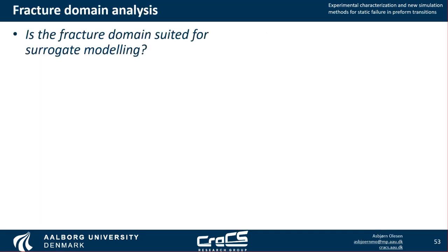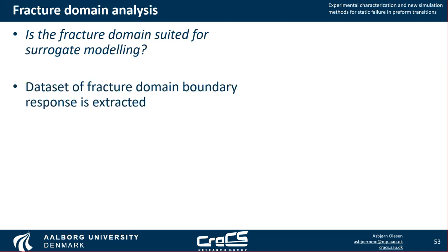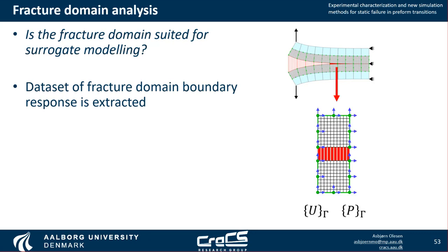Returning to the second question, whether the fracture domain is suited for surrogate modeling, the way that we want to investigate this is to extract a data set of the fracture domain boundary response, and then investigate the complexity of this data set. The way that we do this is that we take our DCB model, we run it through a number of boundary conditions, and then for each fracture domain defined in this model, we extract all of the displacements, and then we compute the reaction forces required to put that displacement in equilibrium for a fracture domain.